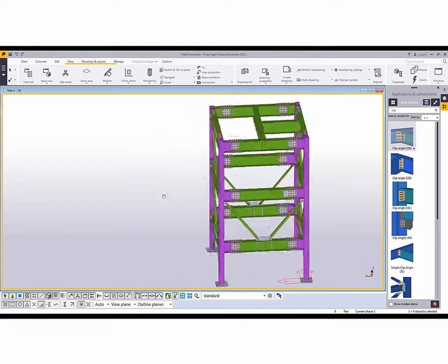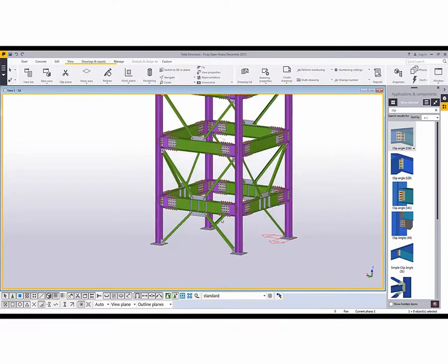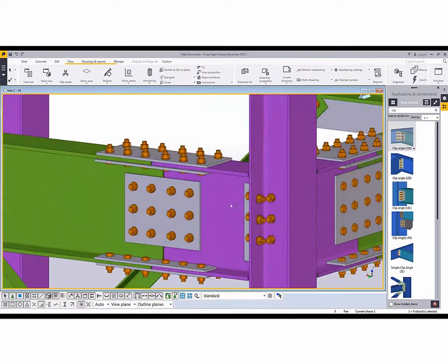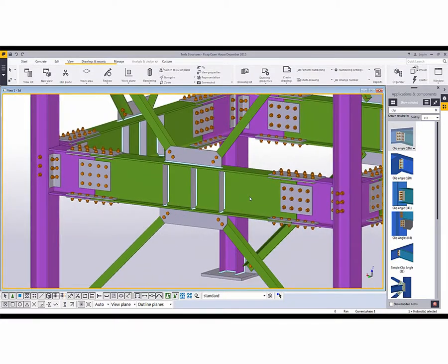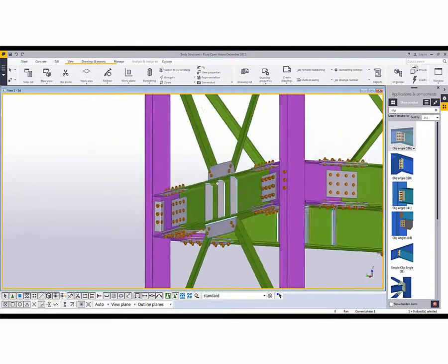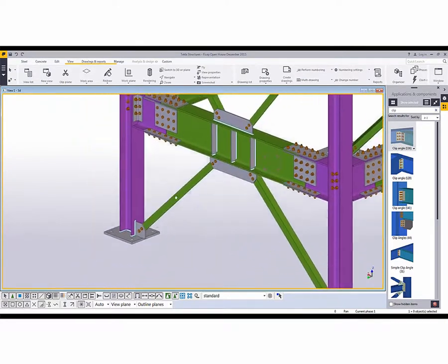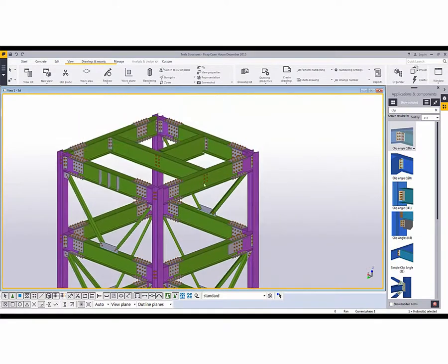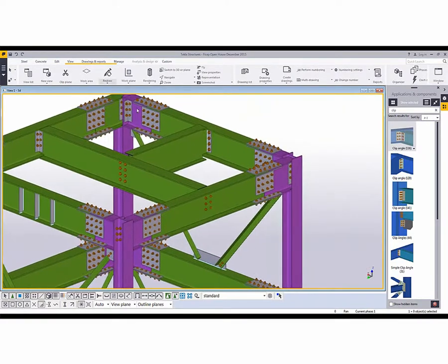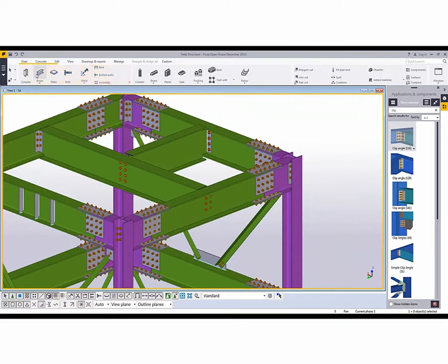I'm going to take a quick look here of linking a Tekla model down to Steel Projects PLM software and ultimately down to the Ficep CNC machines. Here we have a typical Tekla model: bolts, copes, welds, plates, angles, beams, a typical variation of pieces and connections. What we'll do is simply add another piece to the model.